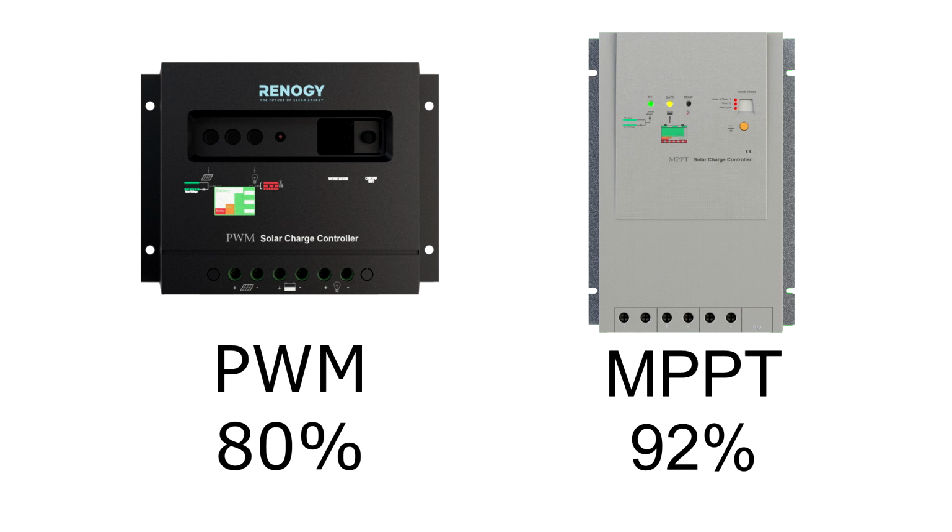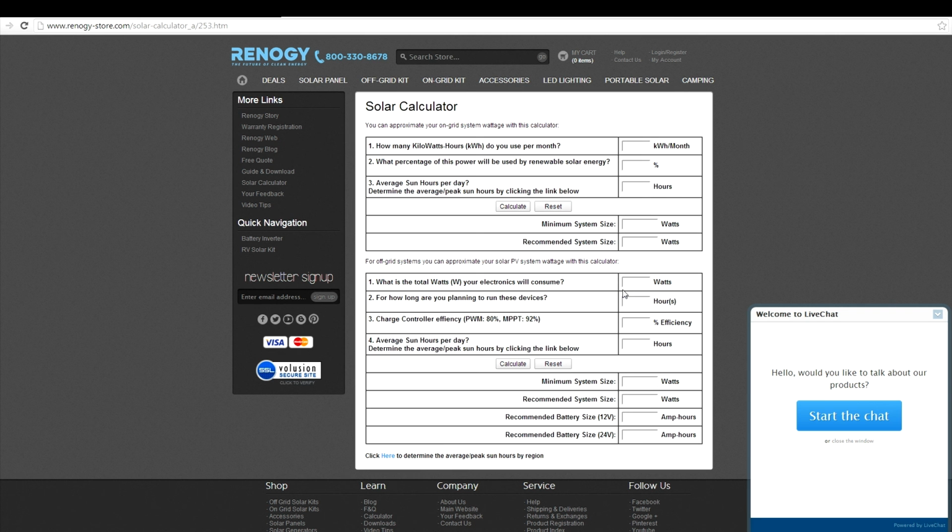For more information on charge controllers, keep up with our video series or contact us and we'll give you some more information regarding them. Lastly, determine your location's average peak sun hours from the chart we showed earlier. For off-grid calculations, we highly recommend using the lowest value possible for your location due to the fact that users of off-grid systems may not have another power source available, and this lowest value will help you compensate for the worst-case scenario with respect to solar conditions.